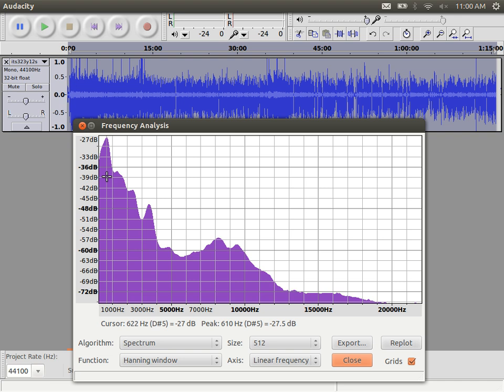And then there are some other peaks. We see the next one, this small one down here, this one here is at 1321 Hertz. So the strongest signal was around 600 Hertz, and it gets weaker for the higher frequencies. Most of the signal strength is concentrated in this area. Okay? As you see, it gets weaker and weaker down to 0.